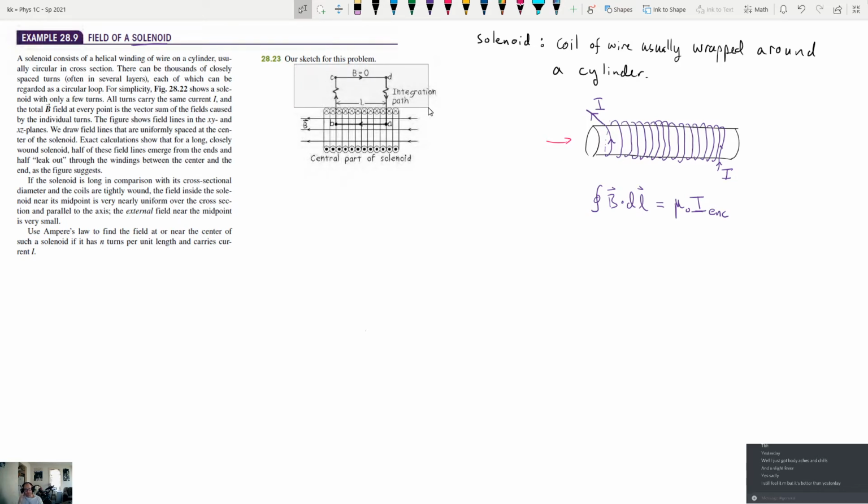It's not true. It will have some magnetic field outside, but if I could show you a demo, it's very easy to prove that the magnetic field on the outside is very negligible relative to the magnetic field on the inside. Because you can use something that's called a magnetometer, which is basically just a little magnet that is able to rotate in 3 dimensions. It's just a magnet on some swivels, basically. And when you put the magnet near the inside, it lines up very strongly with the magnetic field, almost like a compass. But if you put the magnet out here, it's basically no effect.